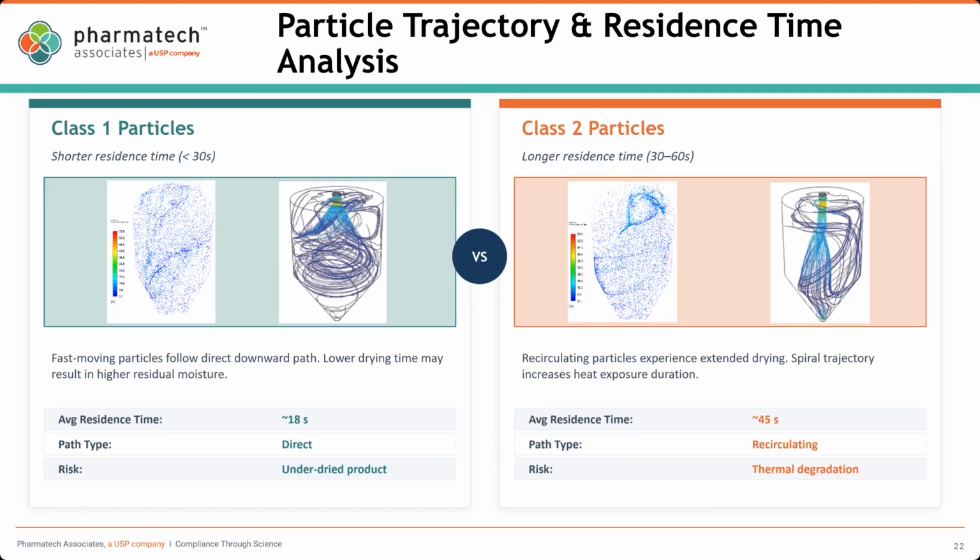Now we have the mass transfer and the heat transfer, or the transfer flux. When we have a smaller particle, the surface area to bulk ratio is larger, so it dries faster, and the particle is exposed to higher temperature for a longer time. So if any decomposition or degradation happens in the D10 particles, because it's reaction kinetics, higher temperature and longer time, we form impurity in the D10.